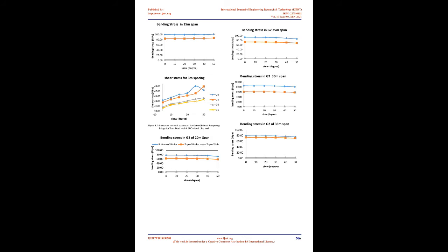In practice, X-type bracings as well as top and bottom chords are made from single or back-to-back channels. The entire parametric study is done with ISMC 125 for cross members and ISMC 100 for top and bottom chords. An important thing to be noted is that the span of the bridge in this study means the distance between supports along the girder, not the perpendicular distance between them. For all bridge types considered, the span-to-depth ratio of 16 is maintained.